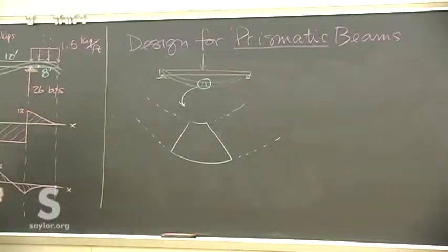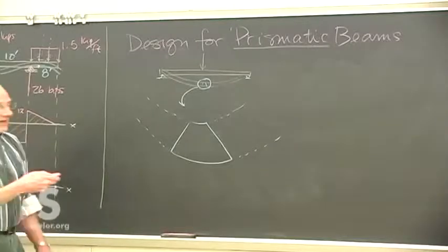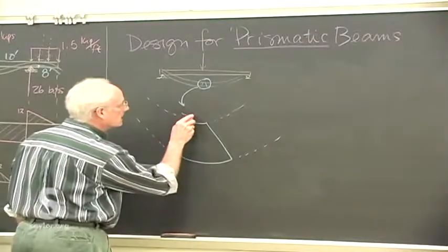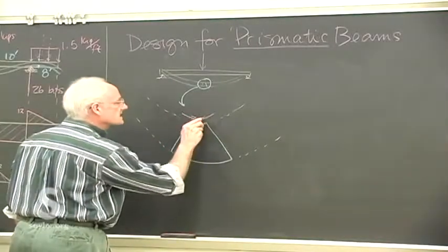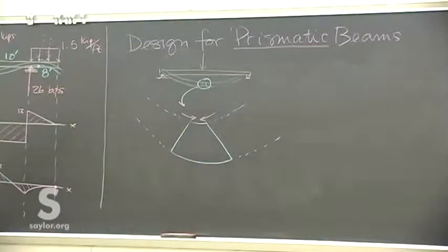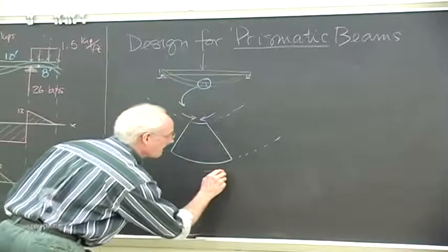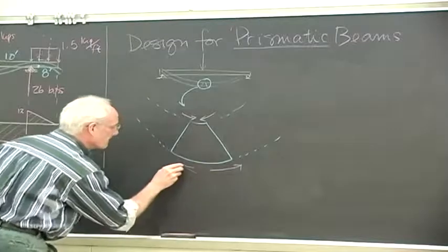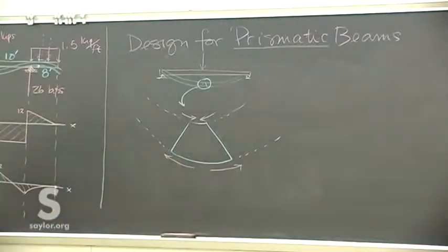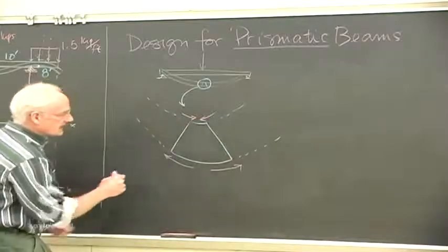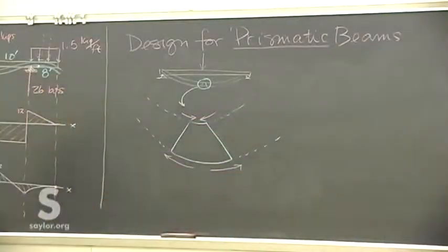Now, obviously, I hope obviously, the top is being compressed because of this bending, and the bottom is being stretched in tension because of the nature of that bending. In a straight unloaded state, of course, there's no deformation. But now there's some kind of compression at the top, some kind of tension at the bottom.